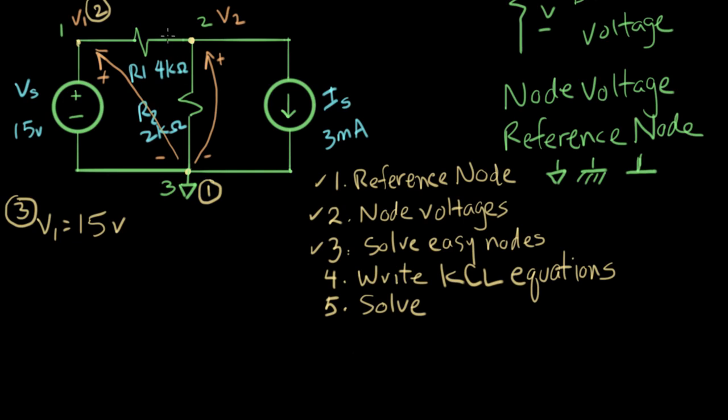And that means we have to identify the currents. There's a current. We'll call that a current, and that's a current. Let me give some names to these currents just to be clear. We'll call this one I1 because it goes through R1. We'll call this one here I2 because it goes through R2. And we'll call this one IS. Now let's write Kirchhoff's current law just in terms of I, and we'll say all the currents flowing into the node add up to 0. So these two have arrows going out, so they're going to get negative signs when we write Kirchhoff's current law.